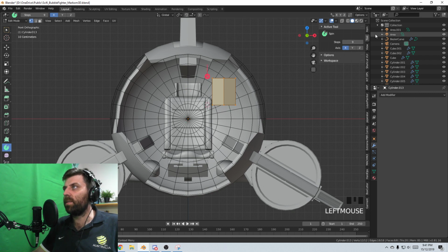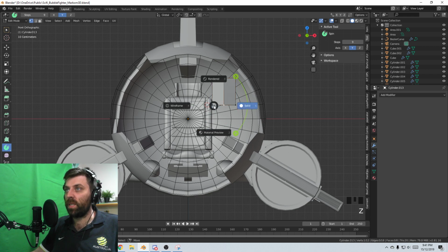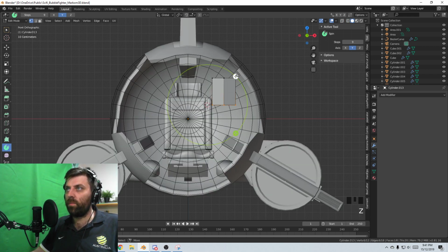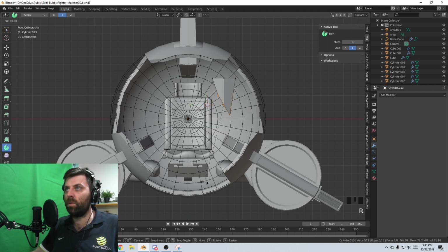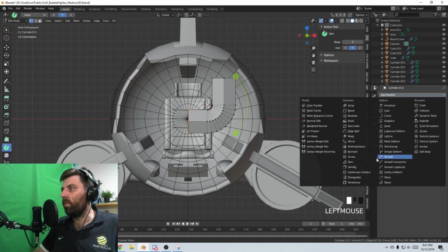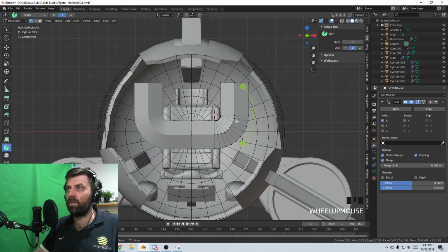Let's select this, and then we'll rotate on the y-axis. Let's select the bottom face first, and we will use the spin tool to go 90 degrees. Hold Control to snap, E to extrude, put in that mirror modifier, clipping, G, X, delete that face, and now it's all joined together.